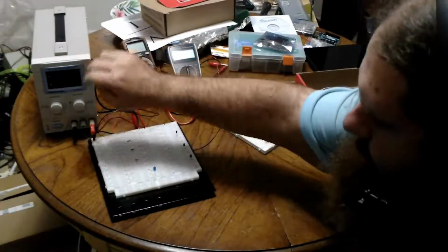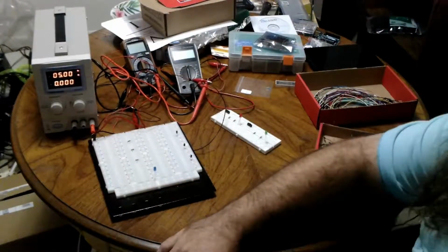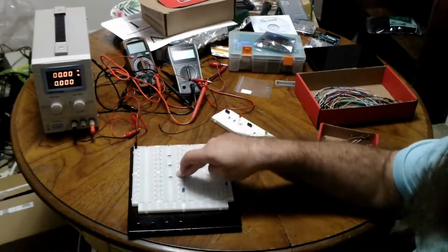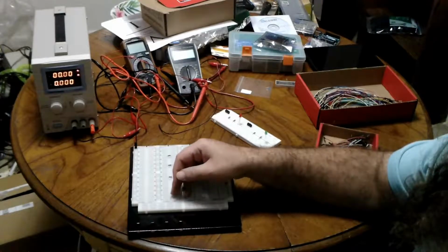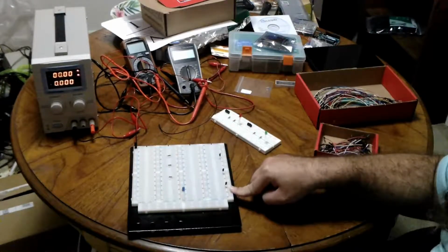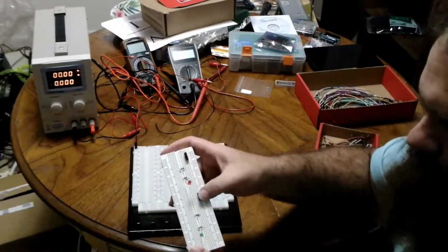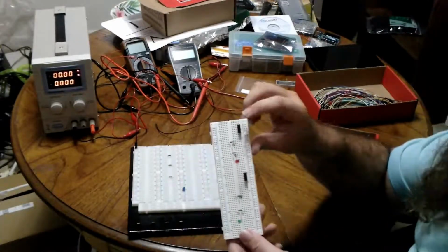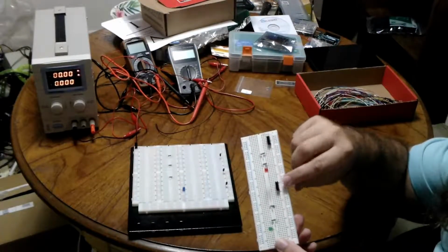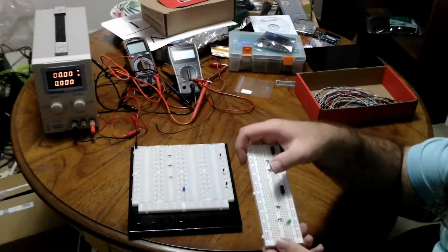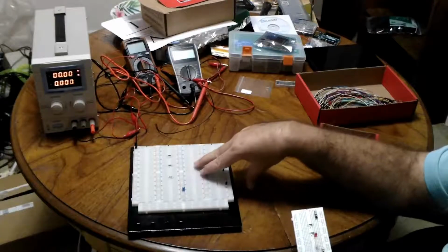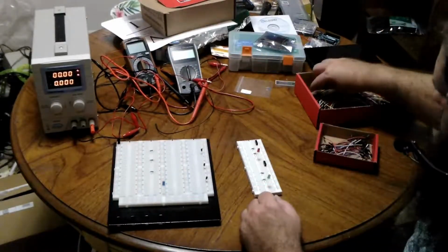So I have here my power supply, currently set to 5 volts and 0 amps. So in my breadboard, I have some 1K resistors, 1000 ohms, an LED that's going to be our output, and 3 NPN transistors. On this breadboard, I have 2 switches with some resistors and 2 LEDs. So this is input 1, this is input 2. The LEDs will indicate which input is on, so you can easily see what we're doing and compare it to the output. So first, I will wire up my switches.